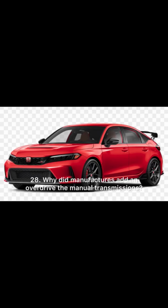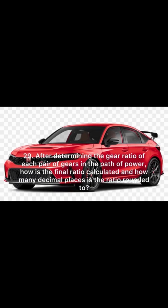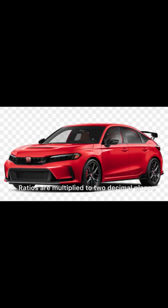28. Why did manufacturers add an overdrive to manual transmissions? Fuel economy, emissions, NVH. 29. After determining the gear ratio of each pair of gears in the path of power, how is the final ratio calculated and to how many decimal places is the ratio rounded? Ratios are multiplied, to decimal places.